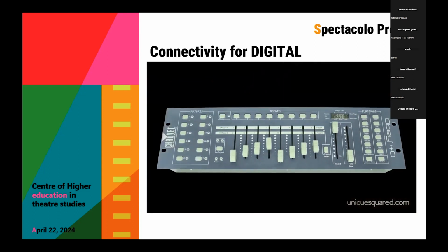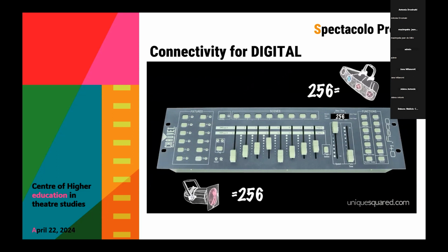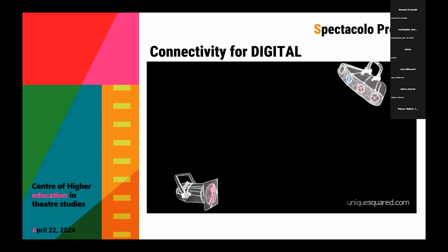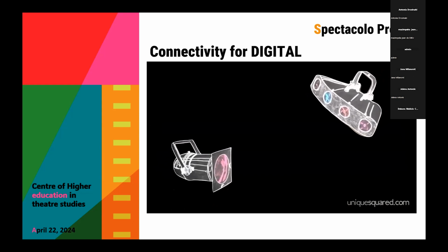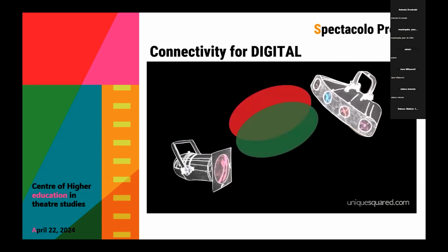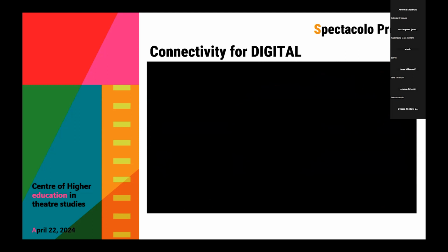You just find the value that corresponds to the amount of power you want on a particular channel for a fixture, and then you set your other matching fixtures with the same value on that same channel for each light. Not only does this help you perfectly match brightness, but it also helps you match color when you're mixing with red, green, and blue channels.